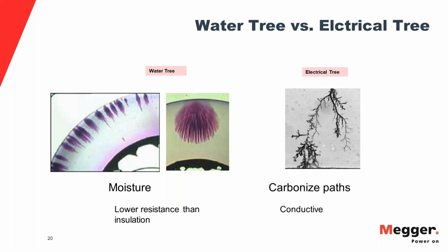The other thing is if there's any moisture in the cable, the leakage current will also trend differently. And if the cable is good, the leakage current will just go to a certain level, and it should stay there in a stable manner over time. And this is how you utilize the leakage current.